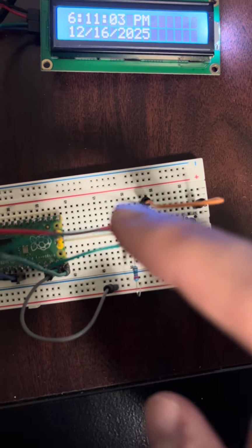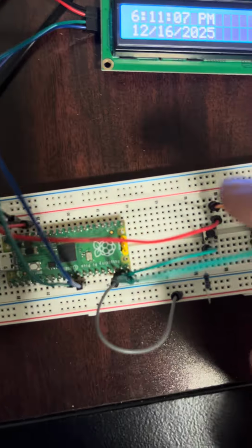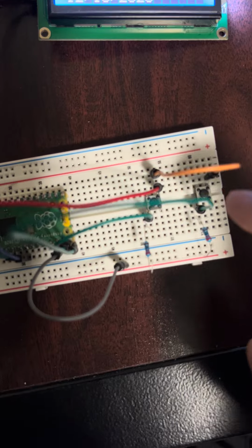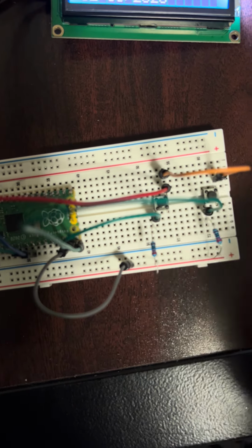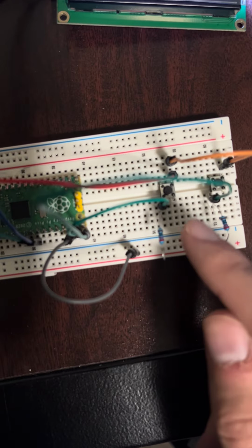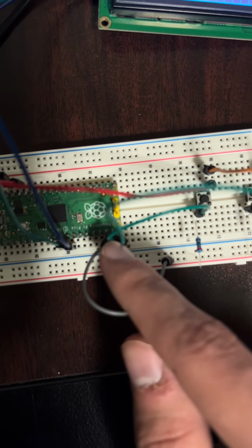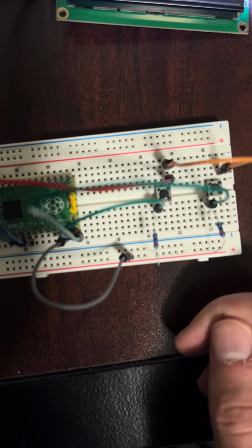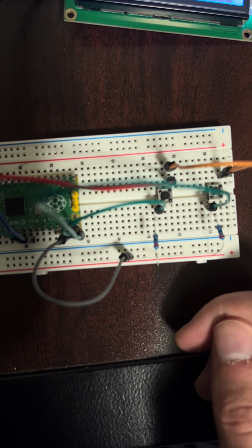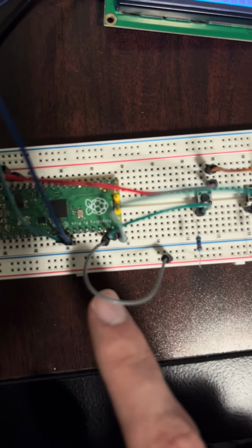These buttons are fed through its 3-volt output, and then once you push down, they'll go from a 0 to a 1 and send a signal into the 15 and 16 pin inputs, telling them that, hey, it's been pressed. Once you release it, it'll execute the accompanying code.